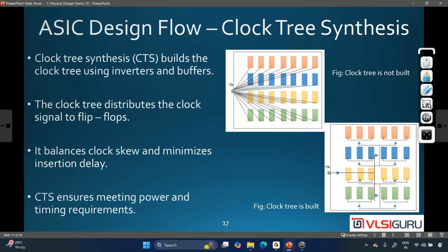We have to do checks like latency check, skew check, setup check, hold check. So all these checks we have to do. These checks you will understand only if you do STA, static timing analysis. That itself is almost a 15 days course. That we'll do. In our course we'll do STA. If you understand that, then you can understand what checks we will do after CTS.